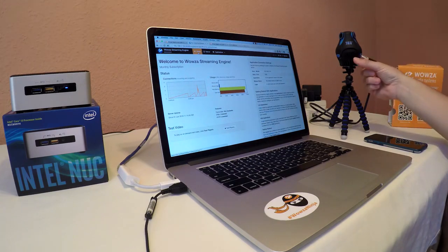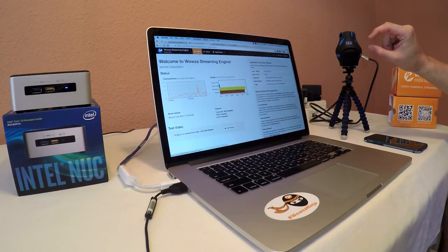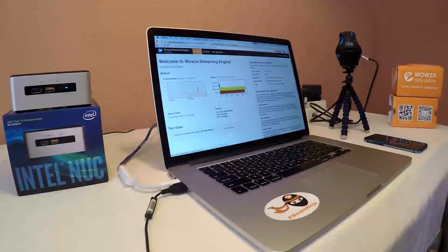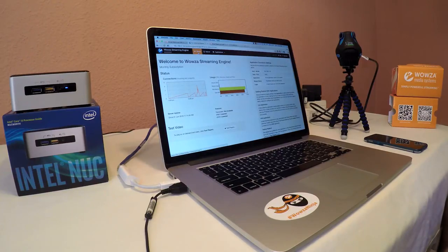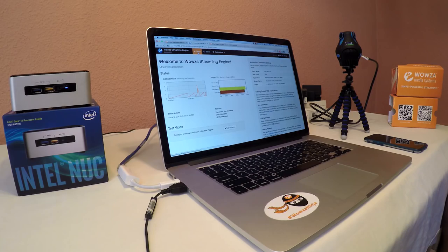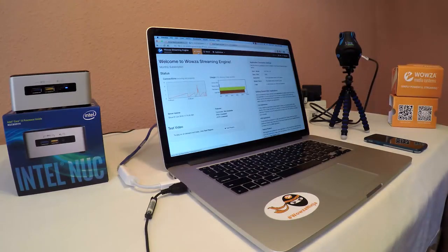The great thing about this PoE addition here is that it will permit me to actually live stream it. So now you can tell it's telling me it's live, and now here in just a second it's going to give me the IP address of what it's found on the router. You can give it a static IP or a dynamic IP. I currently have it set as dynamic, and I have just a very narrow IP range that I'm using to grab this.